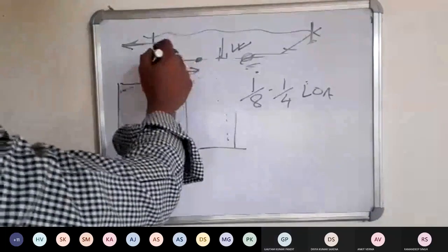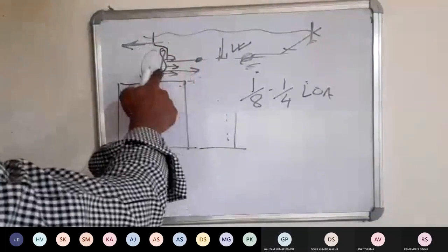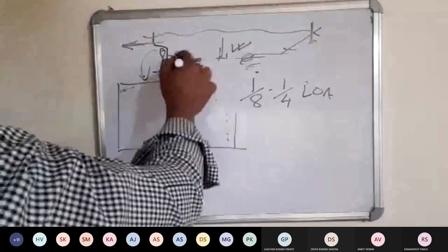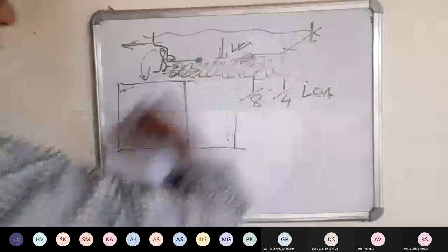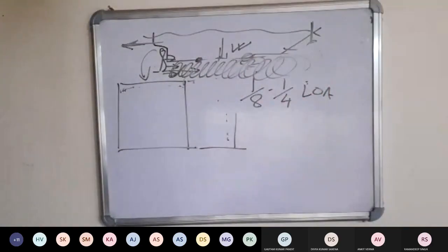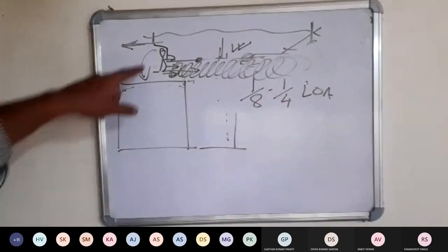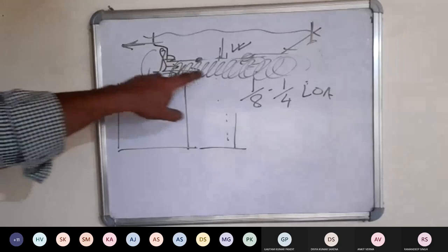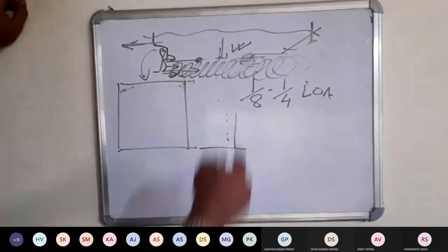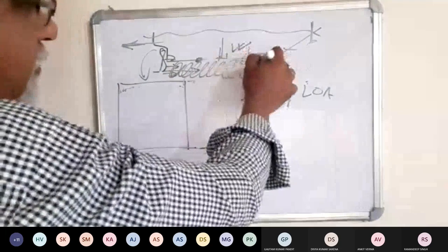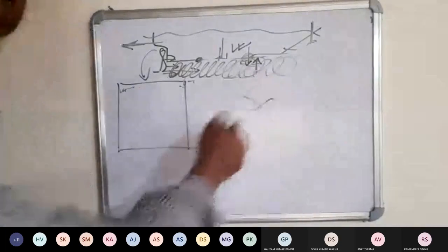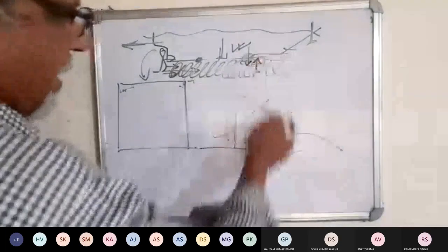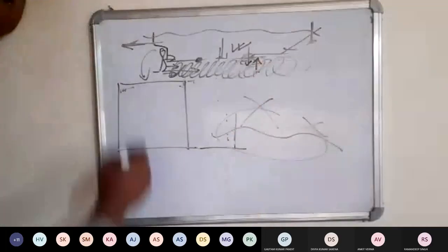Yes, sir. During that, the propeller is rotating and it is churning the water. Near this, a lot of air bubbles are produced. So much churning water, producing so many bubbles that nothing passes through this. No signal is going here. So if the depth is here, the depth is not readable.